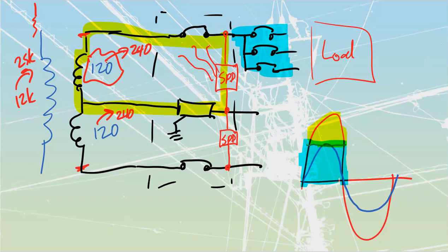We have had a couple of names for these things in prior iterations. SSA, secondary surge arrestors, generally speaking, are ones that would be on top of pole lines, as well as TVSS, transient voltage surge suppressors. Those were, generally speaking, components that would be inside of equipment. Let's talk about where surges themselves come from. So this tells us what the surge suppression is supposed to do. It's just going to top the voltage off. That's all it's doing. It's beheading that, discarding this as heat off of the surge protective device itself, and only allowing the good usable value of voltage to pass through.